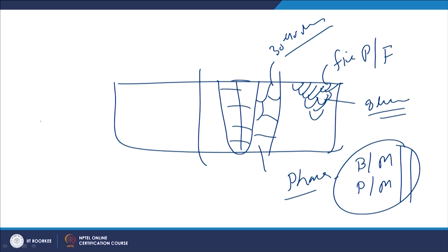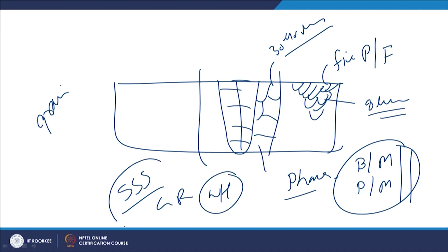So, the grain size and work hardening are not as effective as the kind of phase transformation, because the phases being formed will be able to regulate the mechanical properties in a bigger way as compared to simple solid solution strengthening, grain refinement or work hardening. So, work hardening will also not be effective if there is no phase transformation in such kind of metal systems.